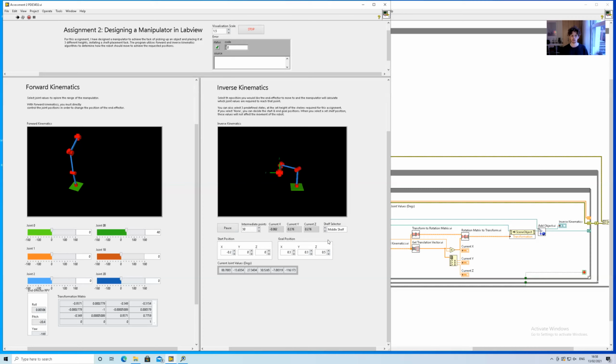And then if we move on to the middle shelf, a bit further down, we can see it's calculated a different motion, and it doesn't look like it would be interacting or colliding with the shelving unit if we were to try and import an STL here. As you can see, this joint is maintaining quite a close radius from the base of the robot. And then the bottom shelf, just 200 millimeters off the floor. Again, I think this configuration would avoid any collisions and could be configured further with a more detailed simulation.